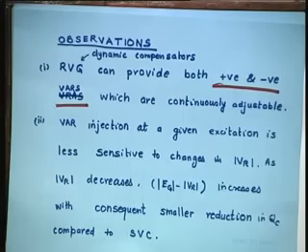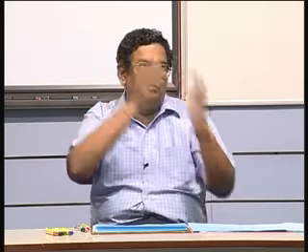Now, this positive and negative vars from the same compensator, this facility is only there in the dynamic compensator. There you have to switch from bank of inductors to bank of capacitors back to bank of inductors. I think you should go to the only place in India where a static var system is in place and working, which is Panki, near Kanpur, about 20 kilometers or so. As and when you go to IIT Kanpur, do visit that place. I am sure you won't be able to make a visit officially because we are not able to do it within Delhi. Where is the question of going to Kanpur? That is the only place we have a static var system in India because it is very costly.